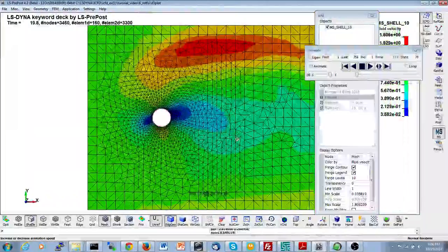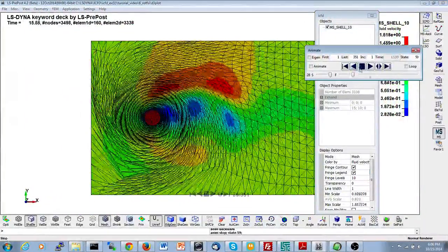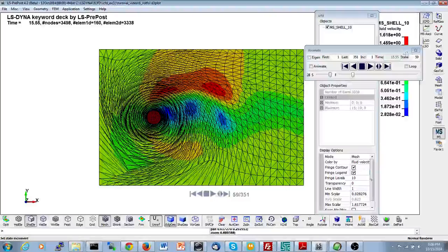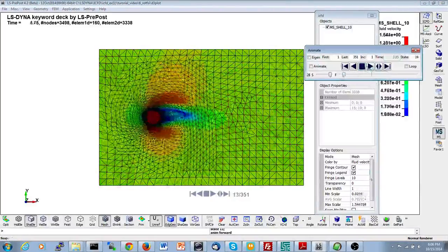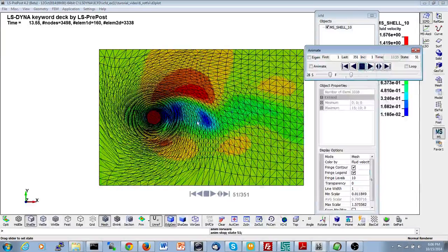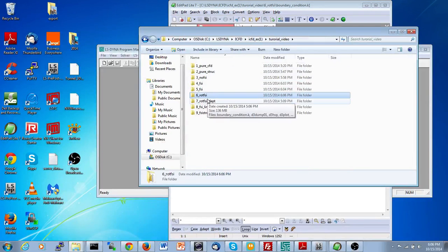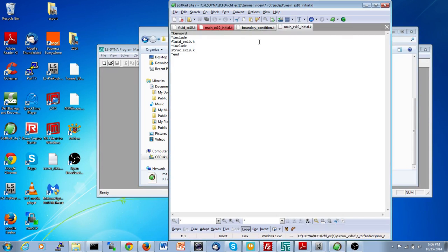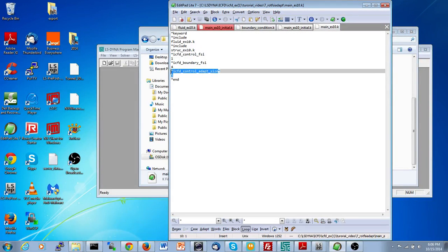So for those reasons, remeshing is avoided, but as you can see in a case like that, we'd like the solver to remesh a little bit more often than only when an element gets distorted. We'd like to say, if the mesh gets too distorted, please remesh. So there's a keyword. The keyword for that is called ICFD control adapt. Let me open here the right file. There you go. So here it's called ICFD control adapt size.